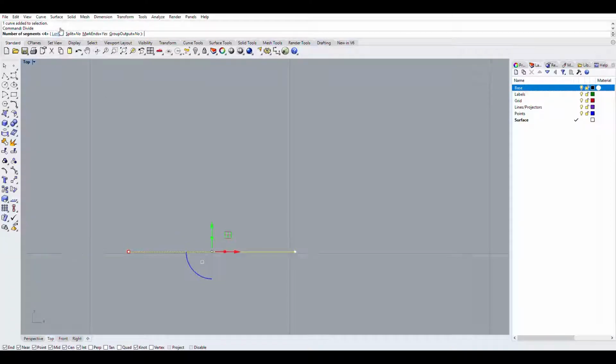You can go in here and click split, so it'll actually split those segments into each individual line. If you don't do split, it'll put a point on each one of those. I'm not going to split our line because I want that to be intact. And I want 10 segments. So now we can see our line right here has 10 different segments: 1, 2, 3, 4, 5, 6, 7, 8, 9, and 10.